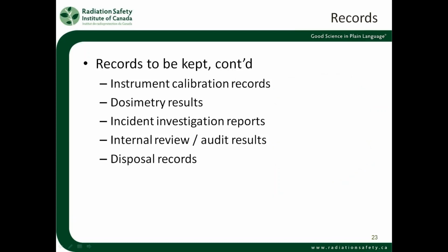We should also keep copies of our instrumentation records, particularly our calibration records. So if we're doing surveys with instruments, what are we doing to make sure that the instruments are reading correctly? And that's an important thing to keep a record of, so that if something was to happen later on, we can show that the survey that we did, at least at that time, the instrument was functioning properly.